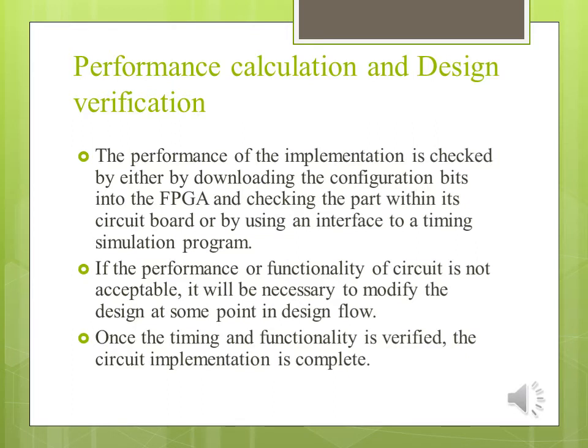Performance calculation and design verification. Once the circuit is routed, the physical paths of all signals within the FPGA are known. It is therefore possible to check the performance of the implementation. This can be done by either downloading the configuration bits into the FPGA or by using an interface to a timing simulation program.